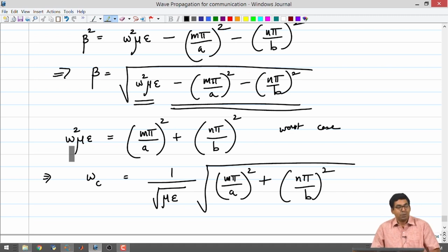Okay. So, we had two unknowns, one is m comma n, and the second one was Ez. What computers can do is find the eigenvalues and eigenvectors of this equation. Eigenvalues will tell you about the omega square mu epsilon, because these are discrete values, and eigenvectors will tell you about the distribution of the field itself, the standing wave pattern of the field Ez.